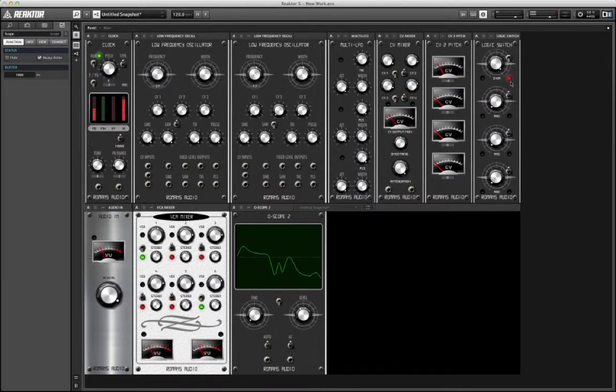Basically, what this means is when LFO1, right now we've got it, if we set it to AND, that means when both of those CV signals are positive, then we get a green light and the gate is opened if it's switched on down, or it triggers if it's up. And the difference between a gate and a trigger: gate stays on the entire time that it's open, and a trigger is just a short burst. Triggers are used in things like drum modules, that kind of stuff.